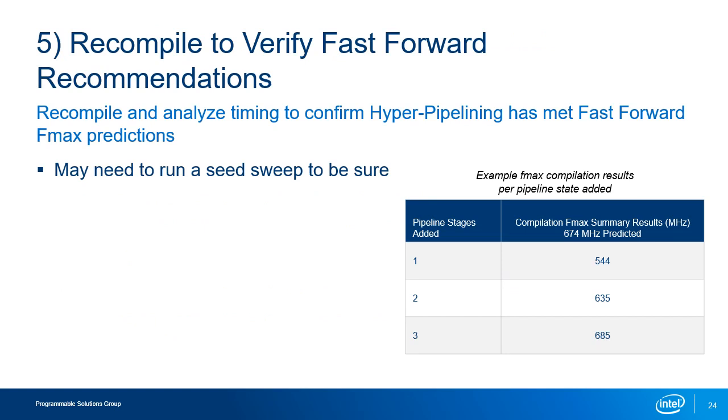After simulating, you want to recompile your design. Remember that fast-forward compile is only virtually implementing the design changes. So after you make your modifications, you should recompile your design and perform timing analysis to check the results.